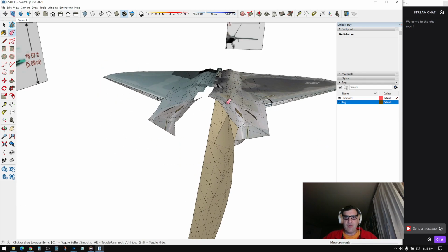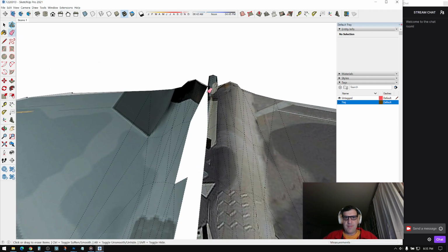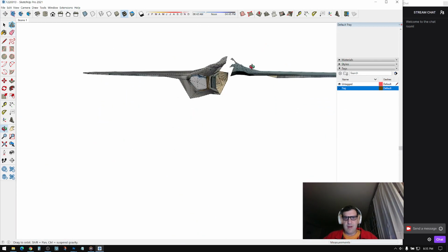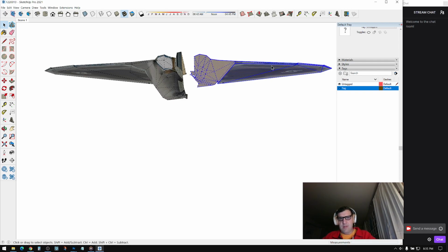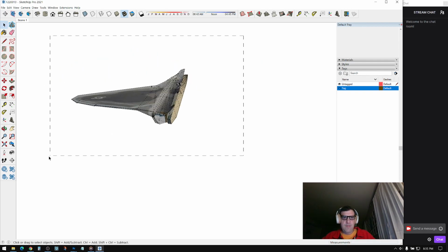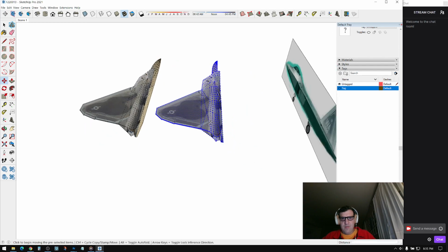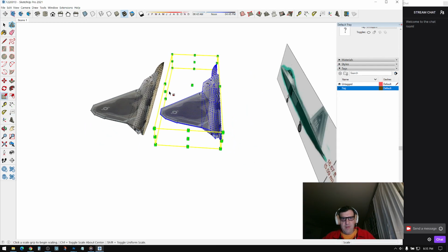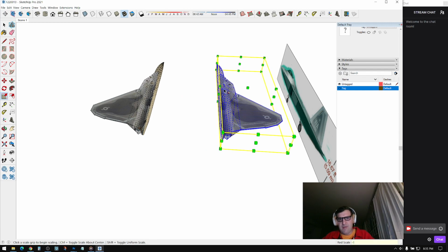Now I'm going to delete with the eraser tool, because I added so much to this side. I'm going to re-mirror it. That should save us a lot of time. Just select it, delete, select it, move, hold Control, and then scale, type in 1 enter, or -1 enter.